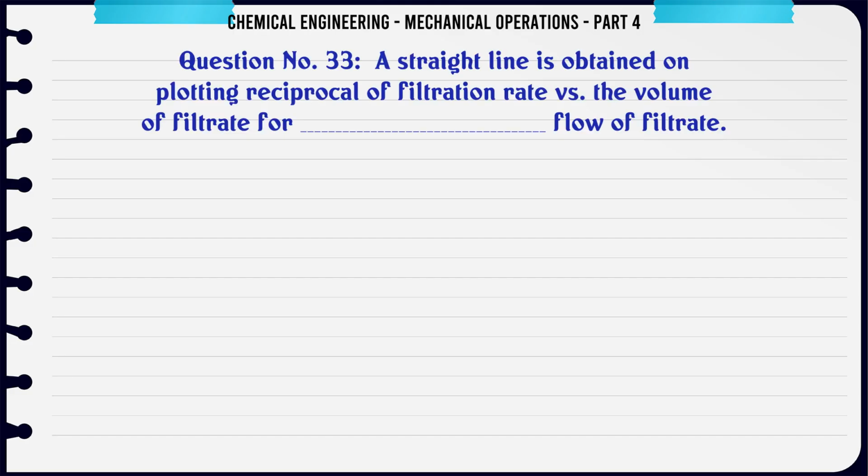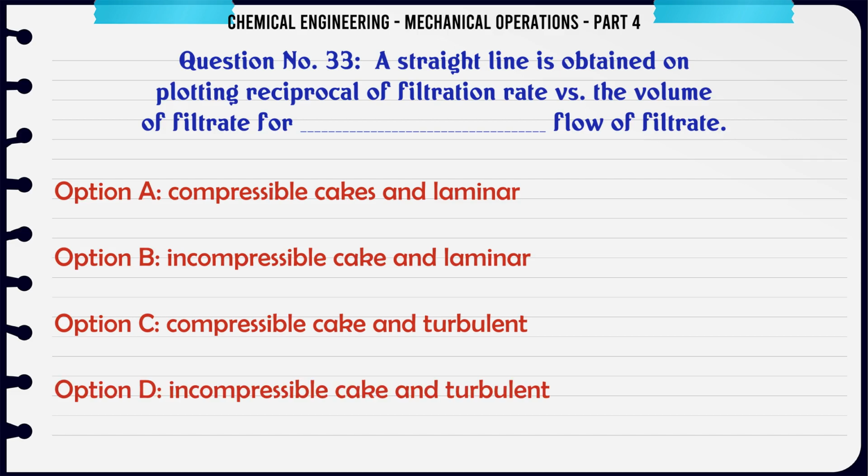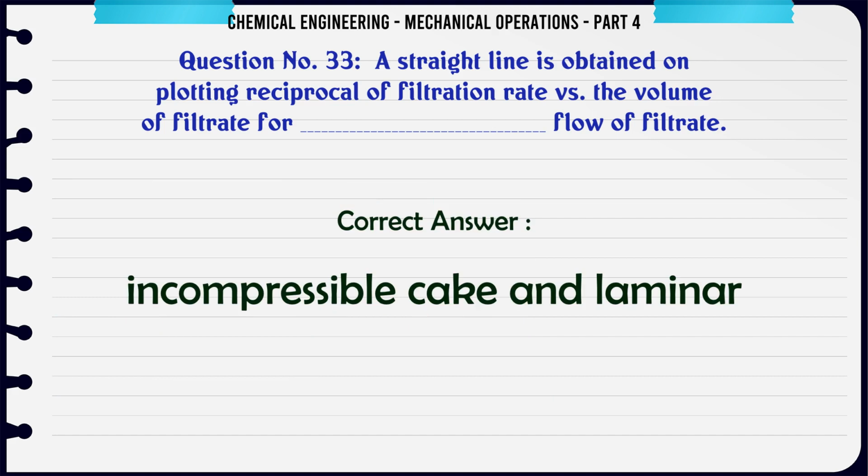A straight line is obtained on plotting reciprocal of filtration rate versus the volume of filtrate for flow of filtrate. A. Compressible cake and laminar, B. Incompressible cake and laminar, C. Compressible cake and turbulent, D. Incompressible cake and turbulent. The correct answer is incompressible cake and laminar.